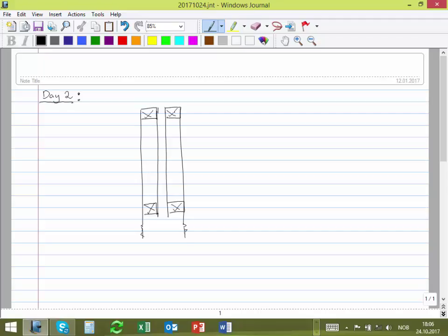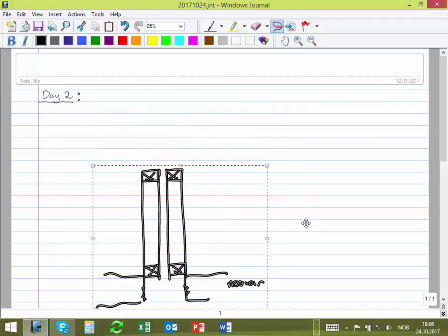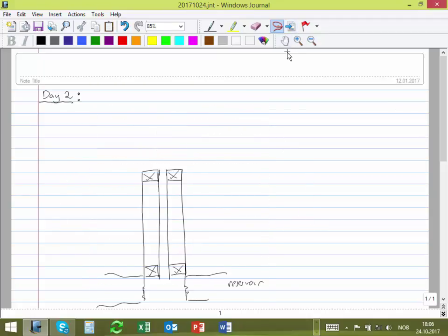And if we go from bottom up, okay, here we have the reservoir. If we go from bottom up, first, what do we find? Which element? From reservoir to surface. What do we find first? The downhole safety valve. Okay, subsurface safety valve. So we find it here around maybe 100, 200 meters below the wellhead, and then we continue, and what else do we find?